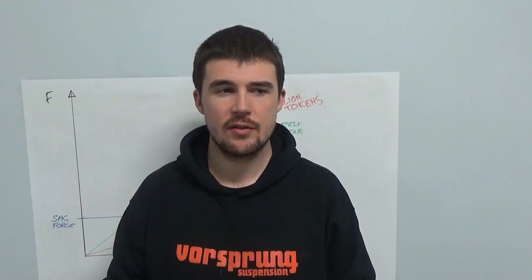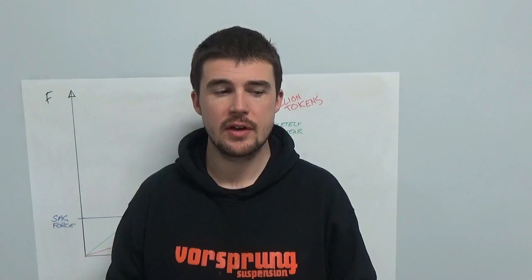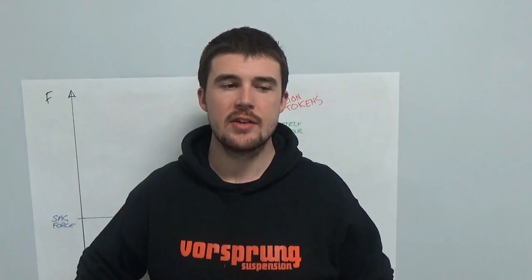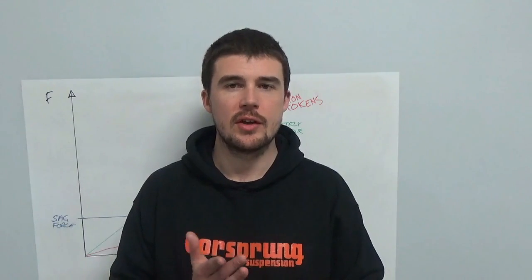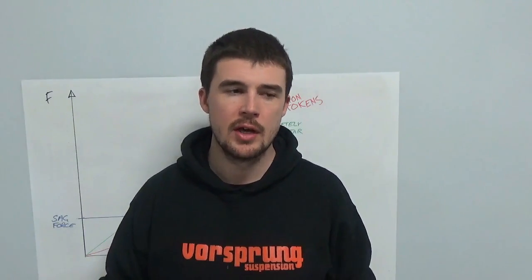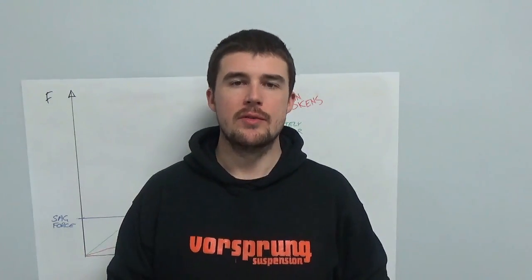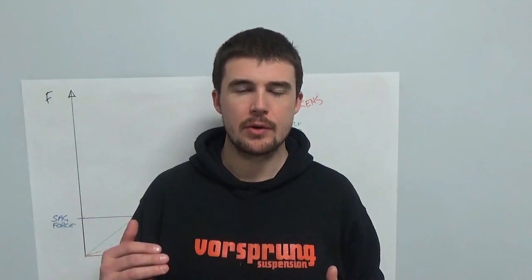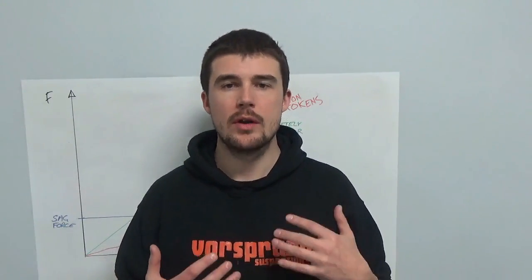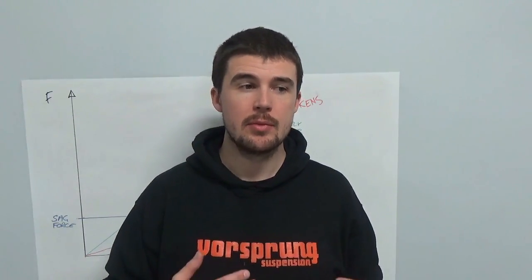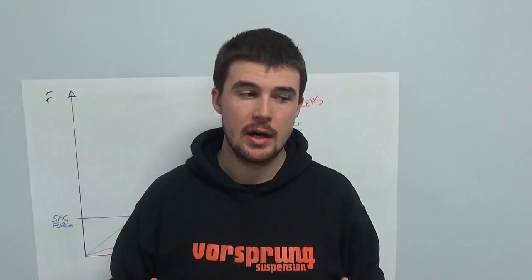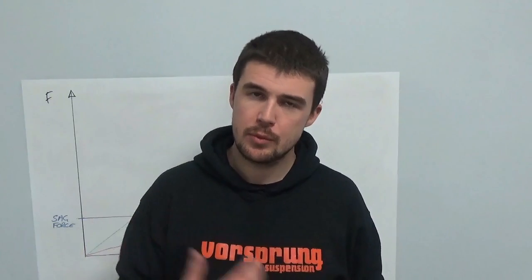So we often have people discussing mid-stroke support of their fork or their shock in some context, and what this usually translates to is that they want to feel like they have more to push against in the middle of the stroke. From a technical point of view, a very linear spring rate will give that to you, more so than a very progressive one. However, what is also very common is that people's perception of what is the middle of the travel is actually quite late in the travel, quite deep in the travel, and they are pushing a long way through.